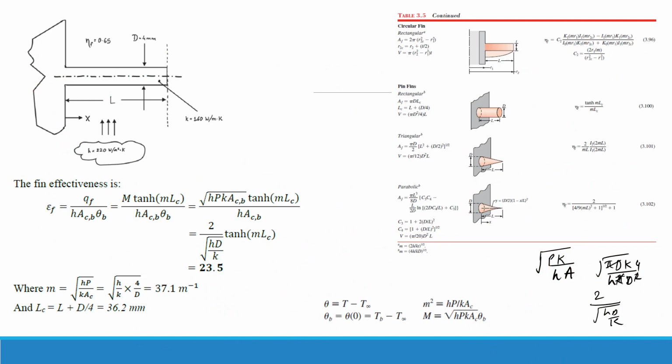So yes, that was all we discussed in today's class. The main takeaway from today's class was we studied these systems whereby the cross-sectional area will depend on the radius or length. So in order to find the resistances, you have to consider a small element and then integrate it along the entire length.